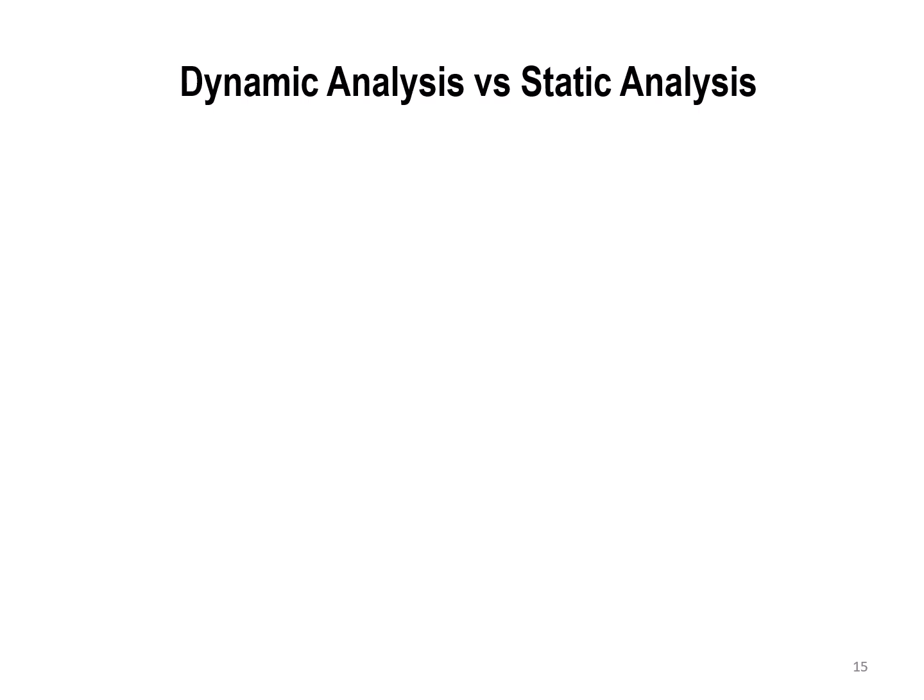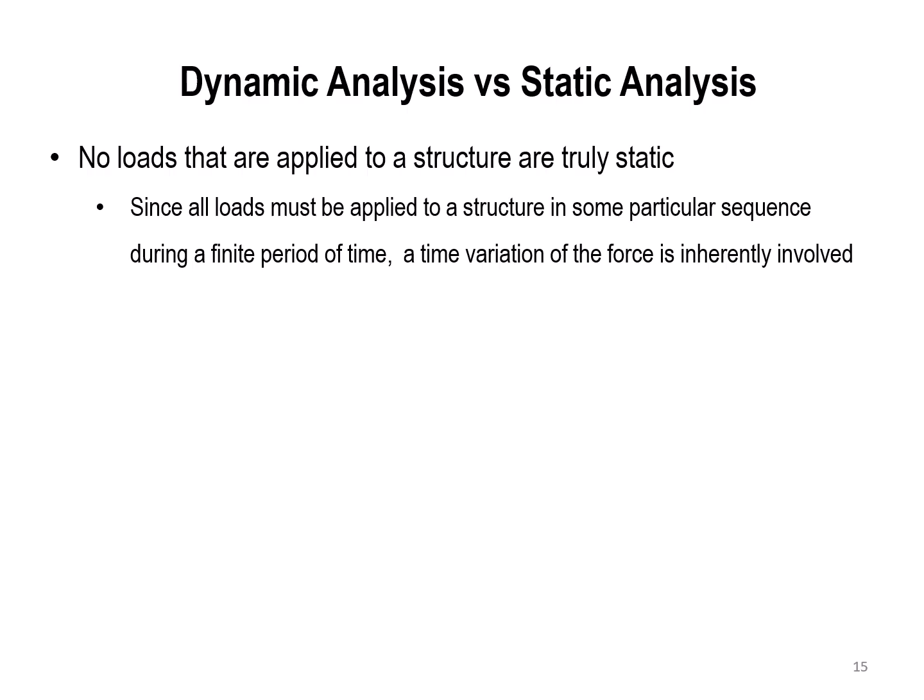Okay, so a simple comparison between dynamic analysis and static analysis: first we have to note that no load applied to a structure is truly static, since all loads must be applied on the structure in some particular sequence during a finite period of time. So the time variation of the force is inherently involved.